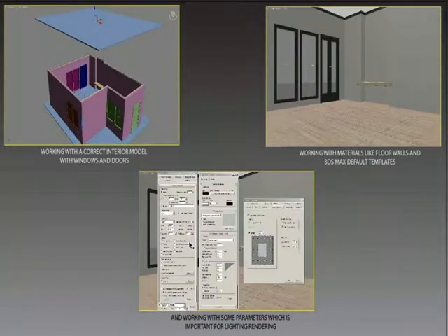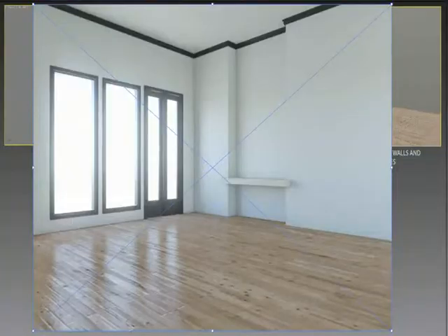I will tell you the combination of final gather and global illumination that you can use in any interior daylight scene. Then I will tell you the exposure control setup, that is important for a photographic, realistic image. And yes, of course, we first turn on the gamma and LUT settings in the preferences. Have a look at our final image. Our final image will look like this.